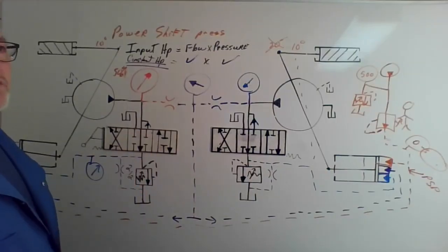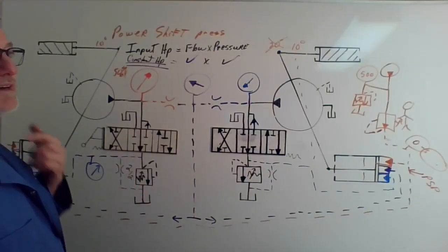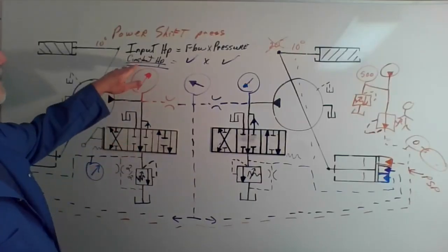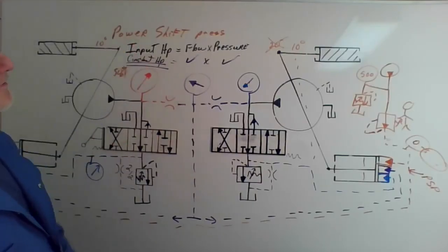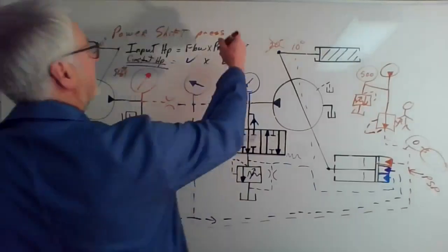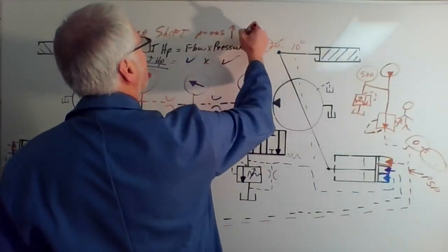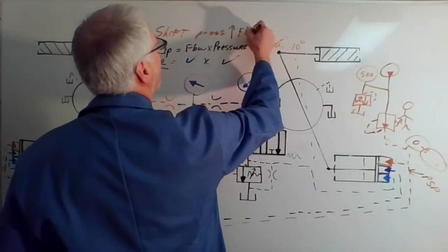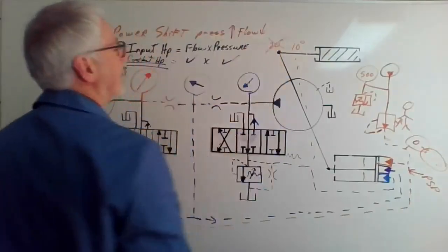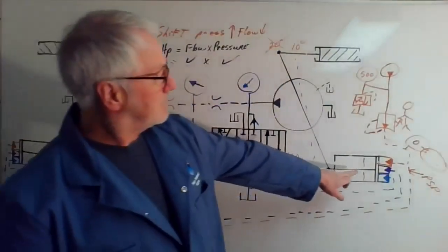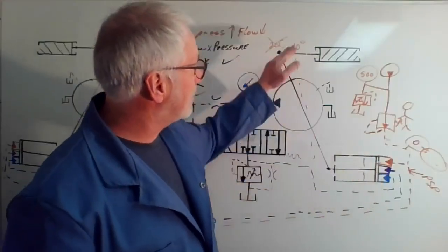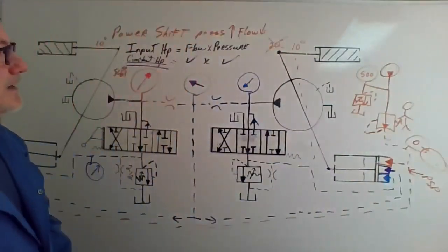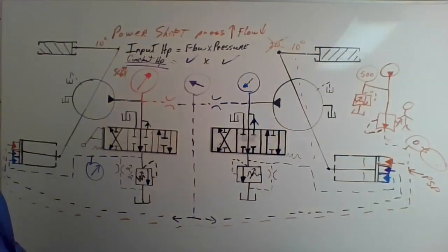Hydraulically, we had to control it first. First and foremost, we had to turn down whatever that constant hydraulic demand was going to be, and that's power shift pressure. So again, if the power shift pressure is high, then flow really goes down, because all three of them are working exactly the same, trying to de-stroke that bias spring. That's the reality of it.